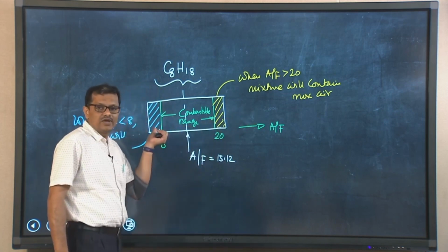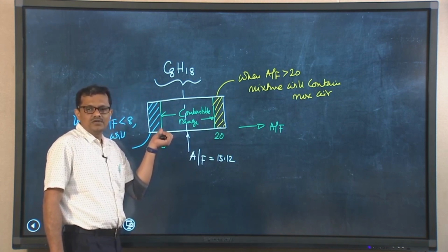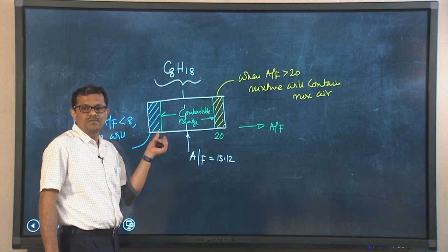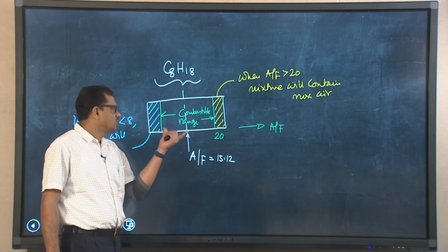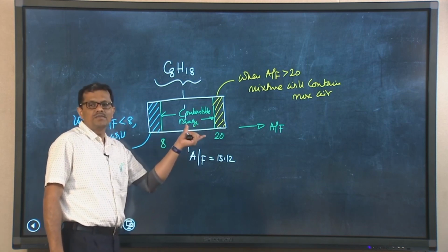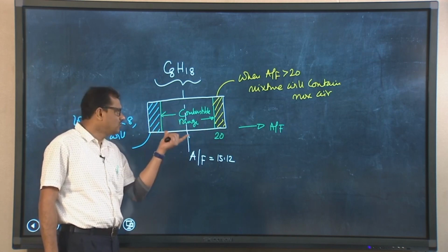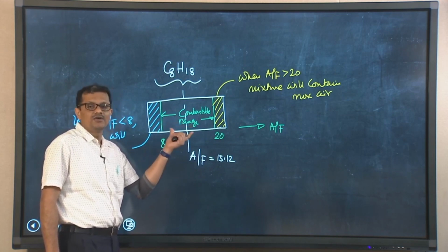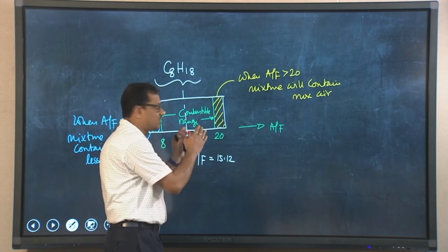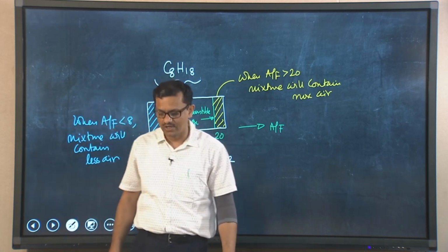When less air is present, that is, rich with fuel, combustion will start and temperature will be produced, but the produced temperature will be absorbed by the excess amount of fuel present in the mixture, and hence combustion will not sustain. So in both these cases, combustion will not sustain and it is not desirable. For any particular fuel, we need to specify the combustible range, and the carburetor should supply the fuel-air ratio within this range, though it is designed to supply always the stoichiometric air-fuel ratio.